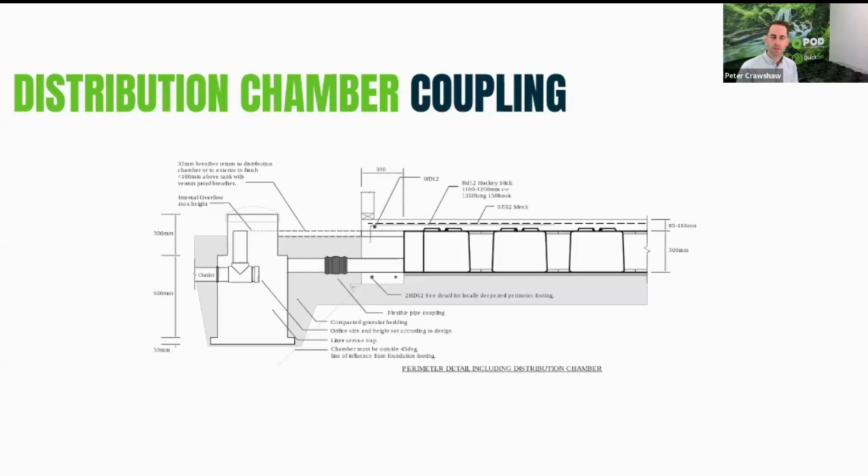So you've got the orifice set there for the outlet for detention purposes. And then you've got the overflow there. If things fill up, it goes over that 100 mil overflow and down out to the outlet again. If it is retention or a percentage of retention, obviously you set that orifice at the height you require, or at top height, you just have an overflow if it's 100% retention. And then that chamber serves as your draw point for rainwater harvesting, which we'll cover off on a later screen as well.